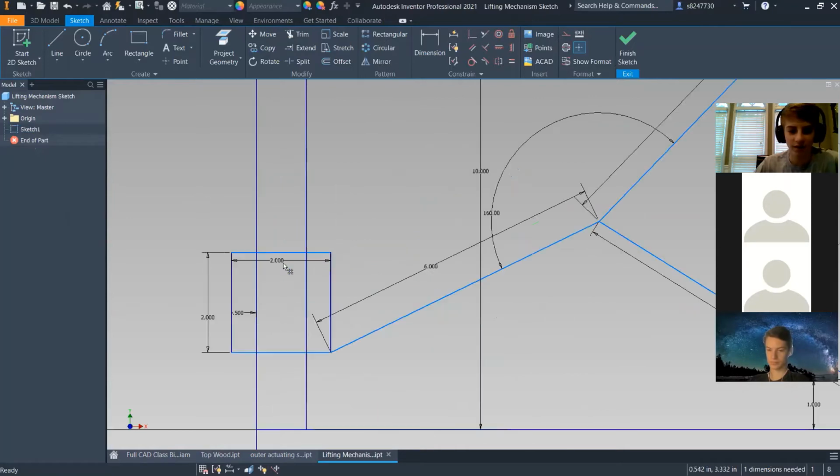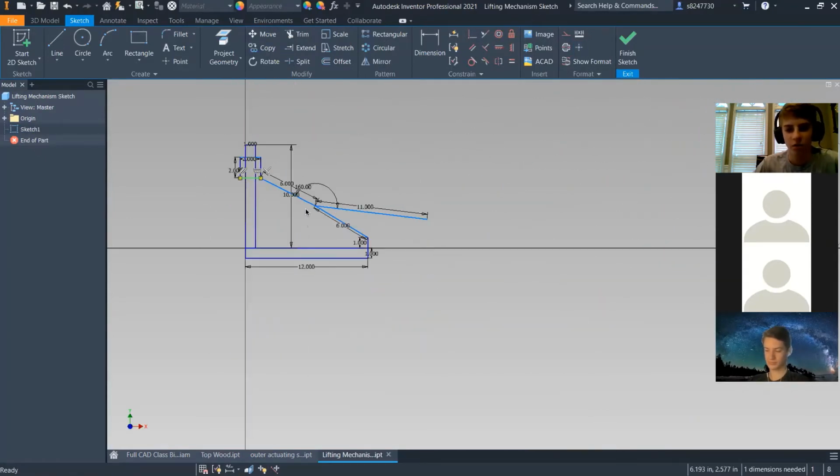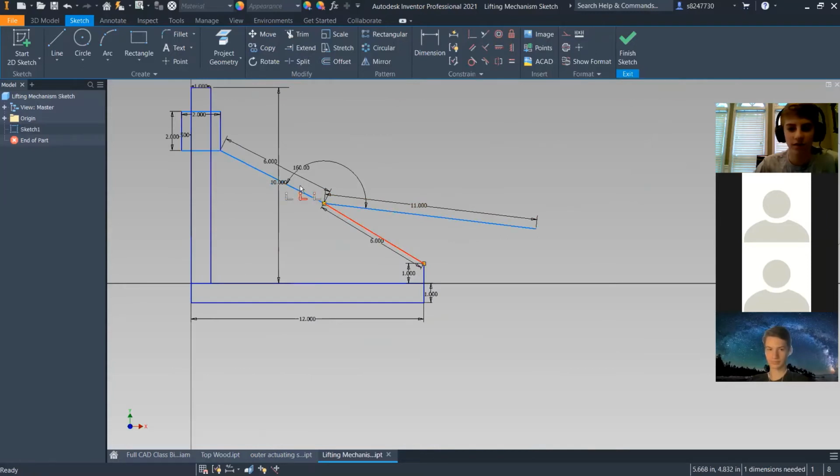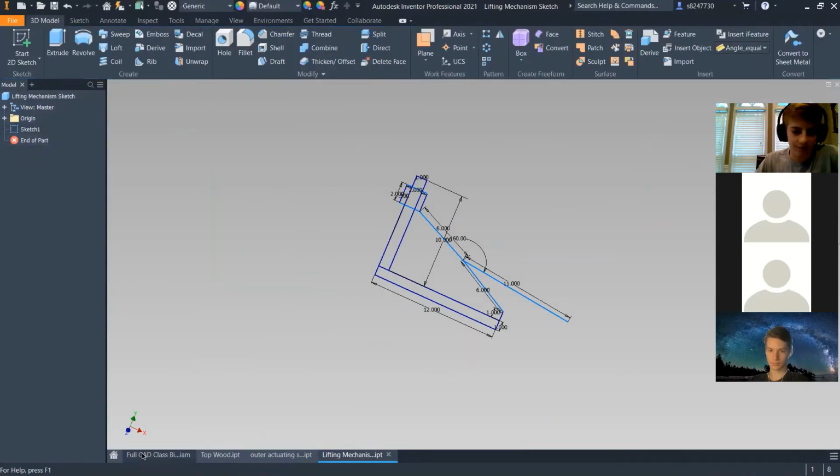So based on this, if we move this thing up, when these two lines are parallel, we want this arm to be contacting somewhere around right here, because that'll stop the bike stand from just flipping back after you get your foot off. So 6 inches is the dimension we're going to use.